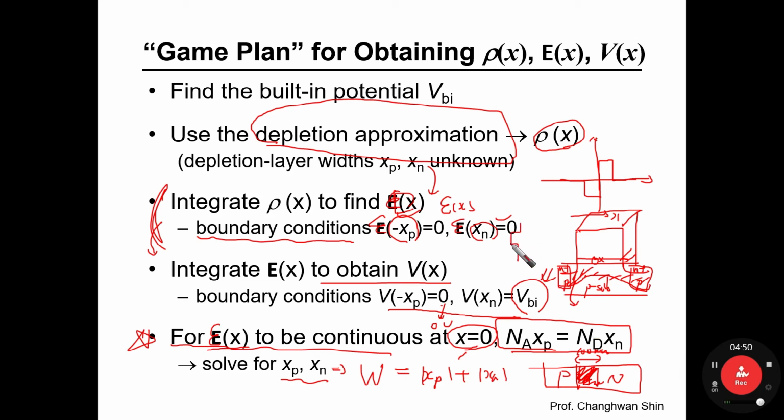If you take a look at the symbol for the MOSFET, some textbooks draw some parasitic capacitance, even here. This parasitic capacitance comes from this depletion layer, below the oxide layer. Then you should have the value for this parasitic capacitance.